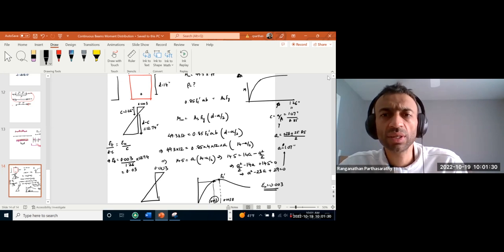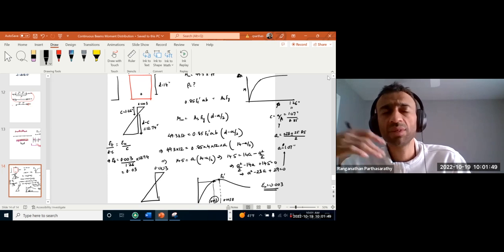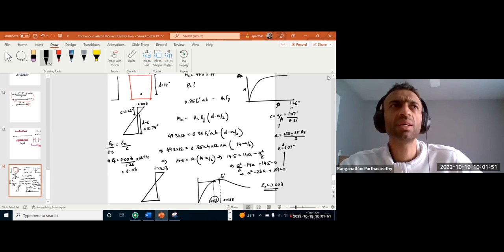We are not concerned with whatever loads are being applied. Of course, if we want to look at deflections, then we will use only service loads. But if we want to look at plastic hinge formation, we have to look at ultimate load, failure and beyond failure also, to see after it fails how much ductility it has.